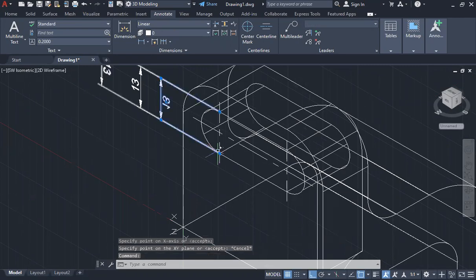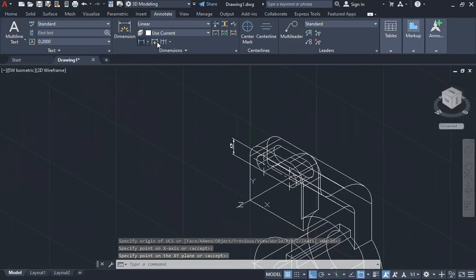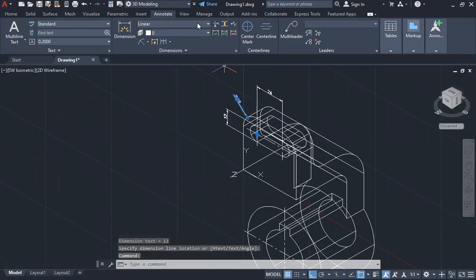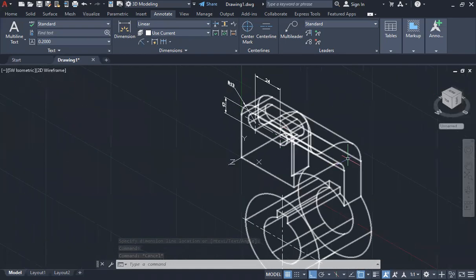So you can have a play around, figure out which dimensions or which surfaces are positive, negative, and apply your dimensioning tools appropriately. So for this surface, X and Y, this is positive. And we can use the different dimensioning tools. So linear dimensions for the 24. And then we'll switch the dimensioning tool to radius to dimension this radius here. Okay. So that's for this surface.